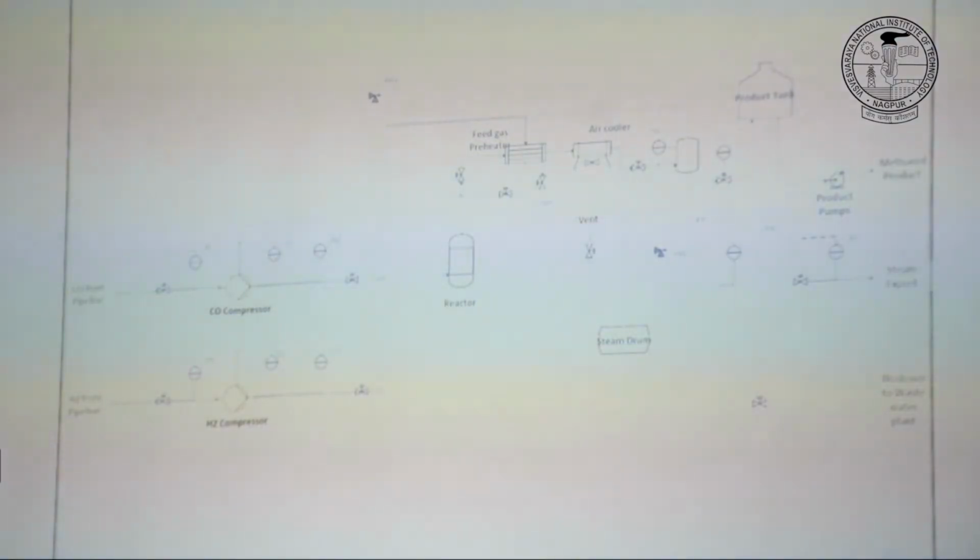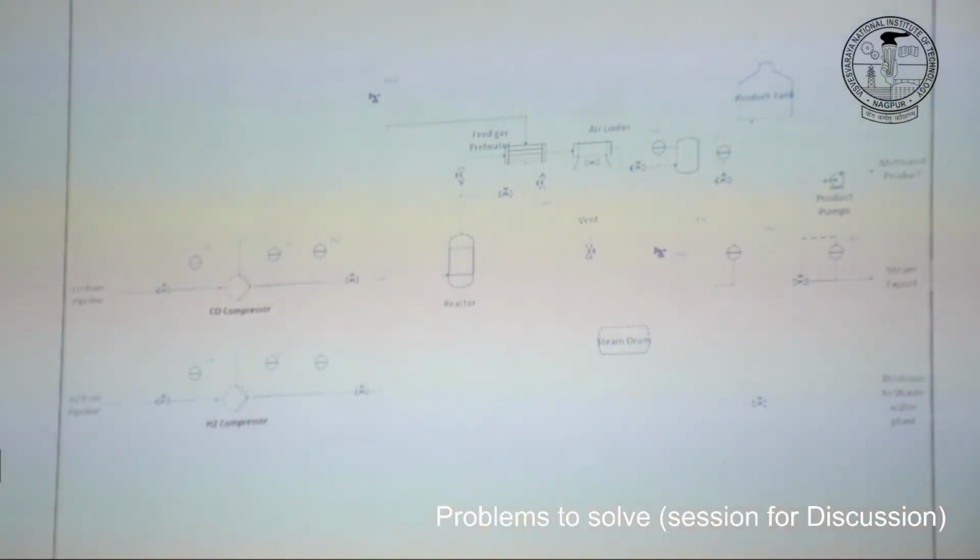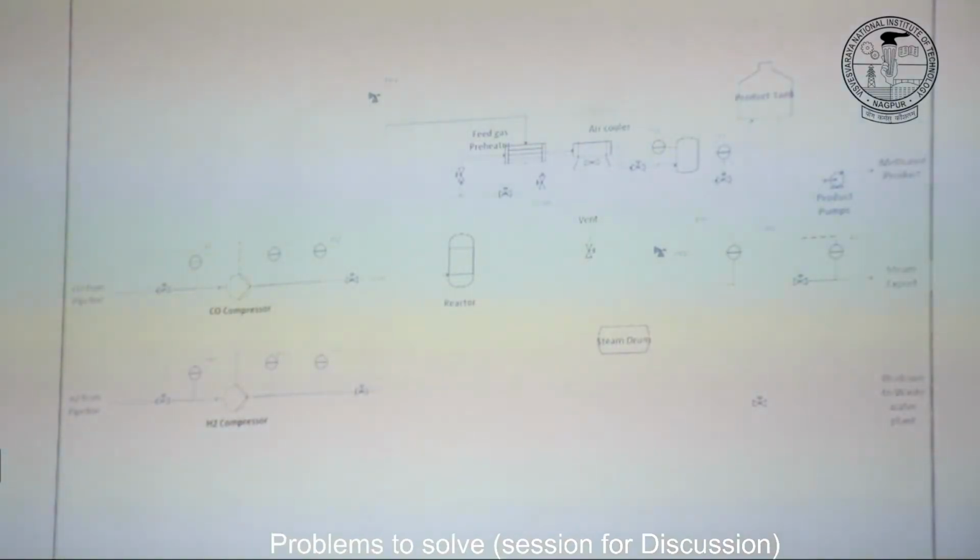So what you normally have from the steam drum, you simply take out a small stream called purge, and in this stream you have all these chemicals removed. To avoid accumulation of all these chemicals, you need to take something out. So you measure conductivity and other parameters, right? There is a continuous stream of purge or blow down, but sometimes you monitor your system, and if it's going high, you could do intermittent blow down purging as well. You simply open the valve, and all this dirty stuff, all those solid particles, are removed.